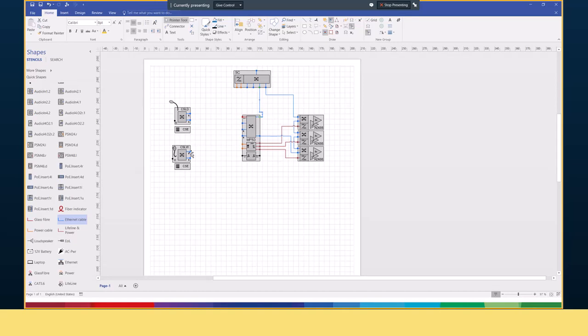I have to connect my call stations, so I also need Ethernet cables for that. That is one. And I have to connect them, of course, to the MPS, to the outputs where I have PoE, power over Ethernet. So I have to connect them to here, where that little flash is. And this happens sometimes in VISIO, that those lines are not very nice.